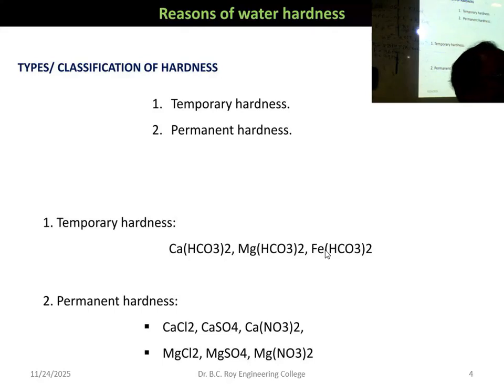Lime. Ordinary lime. Calcium hydroxide. You may take calcium oxide, add into water, you get calcium hydroxide. That calcium hydroxide, if you use, then that reacts with this bicarbonate, producing carbonates, and you get the deposition, just like the boiling. And the benefit, you cannot boil your well.